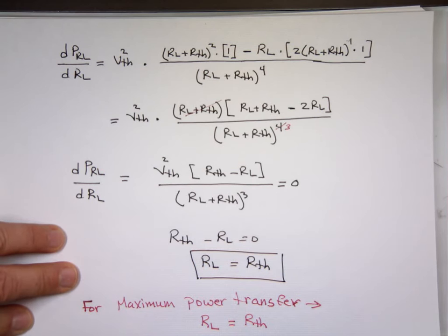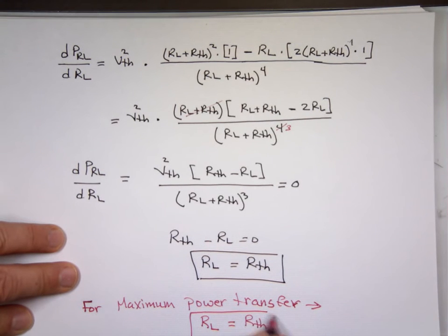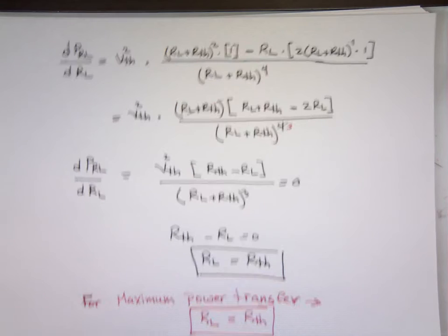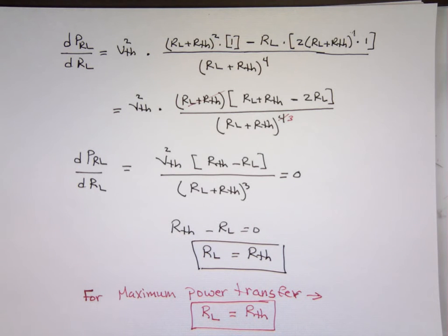That's what you need to have. So if the problem says, tell me what value of load resistor I can put there, make sure that value has to equal R Thevenin. If it is, you'll have a maximum power. Why? Because the voltage now will be half of that, and V squared over R, that'll be your maximum power.